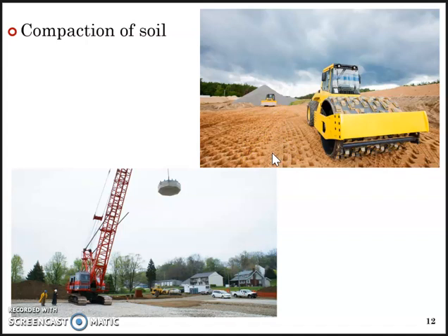Consolidation, on the other hand, is usually a naturally occurring process. A saturated soil, when induced with force, settles due to the expulsion of water, whereas in compaction, you artificially generate a stress above the soil, thereby decreasing the volume of the soil and increasing the density.